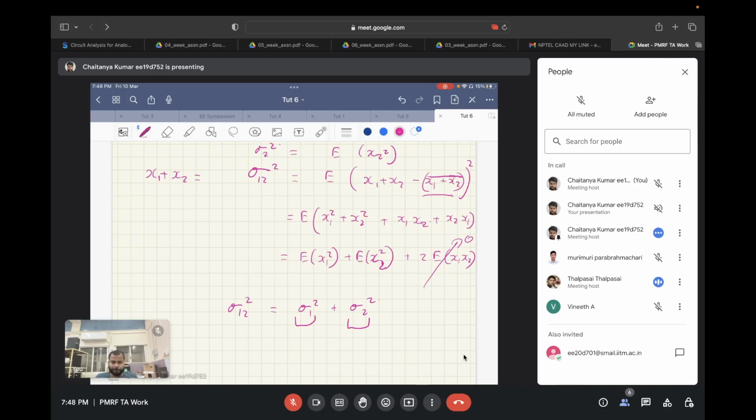Sir, if it is an open loop system, is that how some non-linearity comes in? Yes. In an open loop system, the GMs that sir showed are made of transconductors, that is, transistors. Transistors are non-linear elements. You know the square law model, right? For a MOSFET, current is proportional to (VGS minus VT) to the power 2.